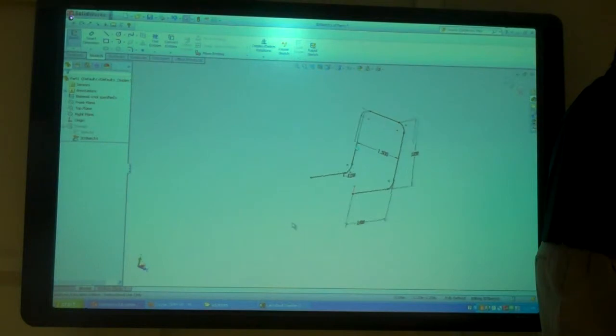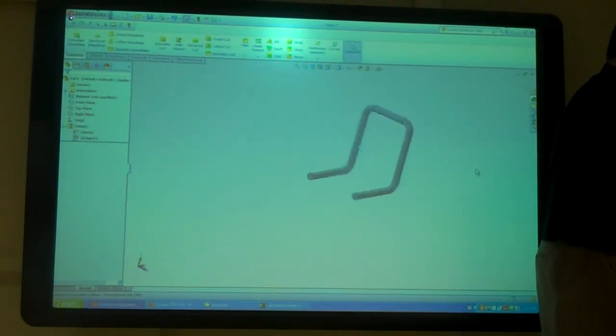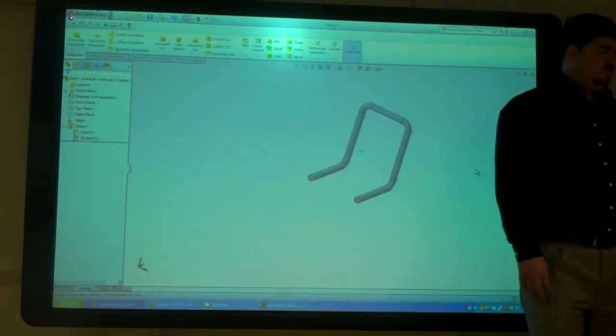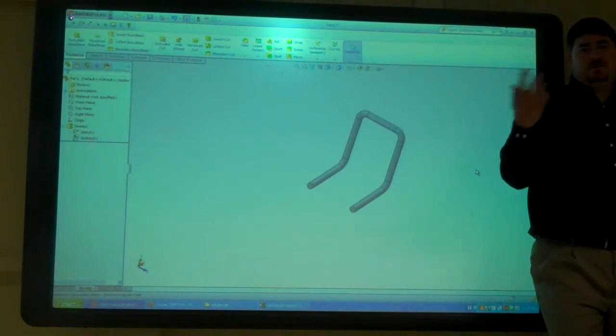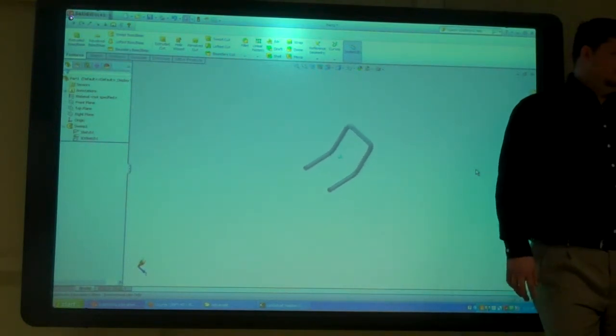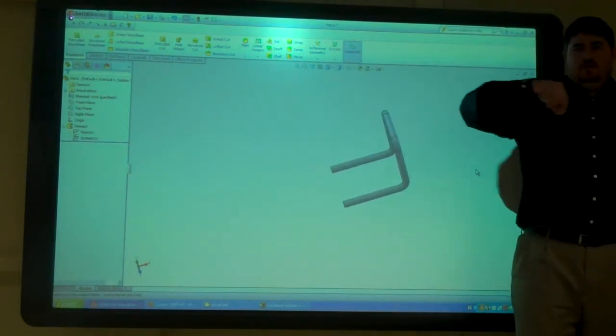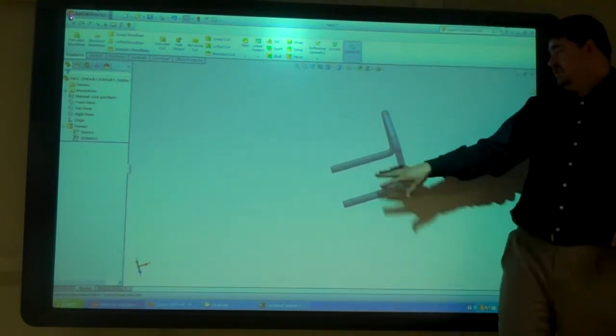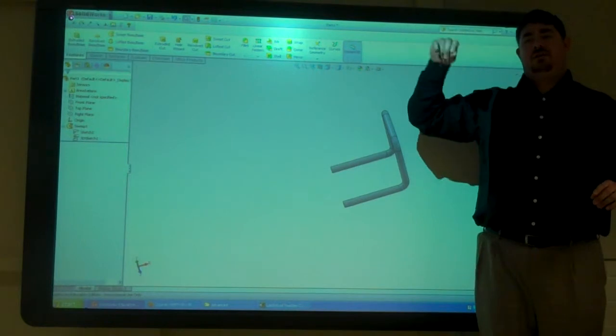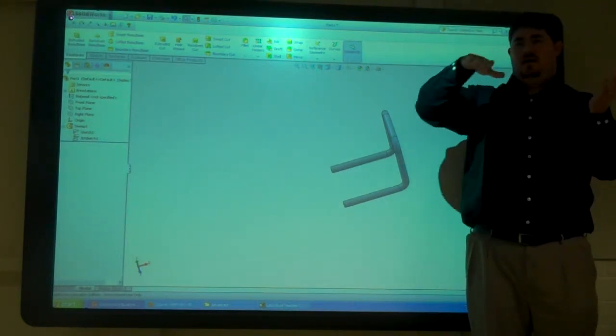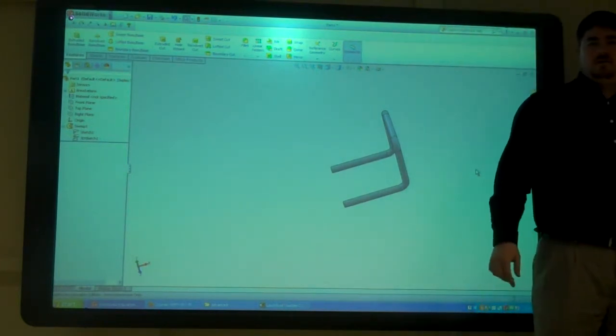There. Like that. So you can fillet and everything and then come back. You don't have to go back. I should have mentioned it first, but I was just showing you a demo thing. So you just pick on the lines, and in this case, you want to do a line and a point, because that's going to make it parallel to that line when you place the dimension.